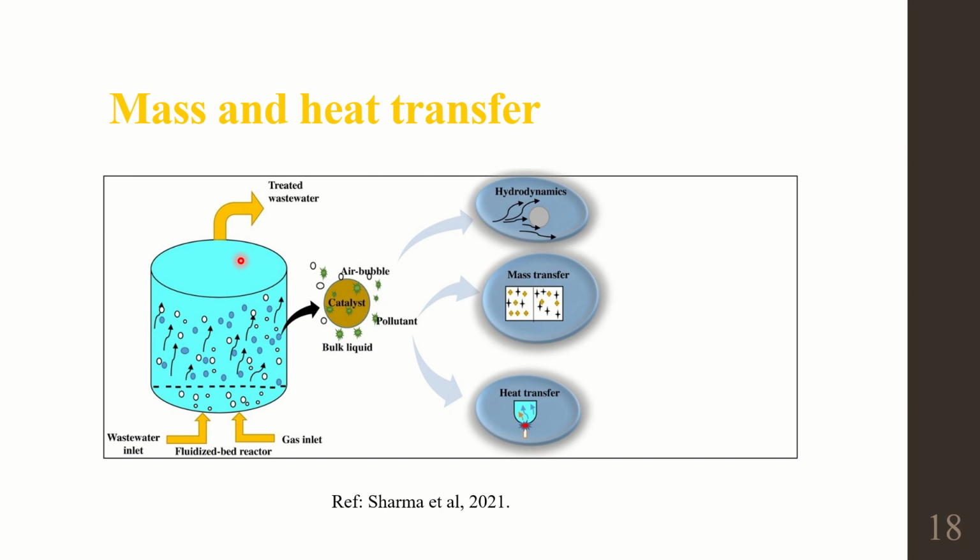So after that, what else do we have? It is the heat transfer. What are all the phenomena by means of which heat transfer takes place in the fluidized beds? We have conduction, convection and radiation. Conduction is between the particles and walls, and convection is when gas is transferring the heat to the particles by means of the motion, or to the wall, that is by means of convection.